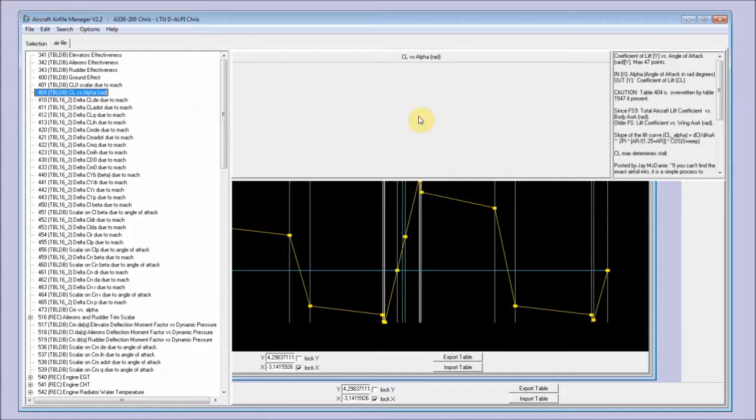So as the trajectory is 0 degrees and the pitch is 2.5 degrees without wind, we have an angle of attack of 2.5 degrees. And now you have to adjust it in a way, again with an assumption that we have small angles, that my lift is equal to weight, and that goes by the basic lift formula, which is Q, which is the dynamic pressure, times S, which is the surface area of the wing, times CL.